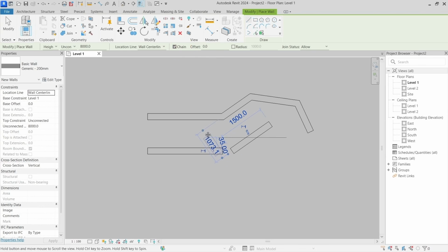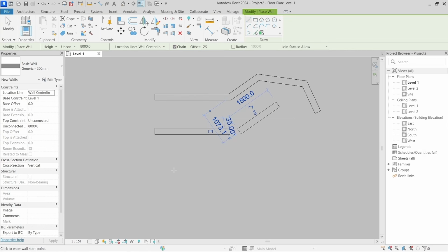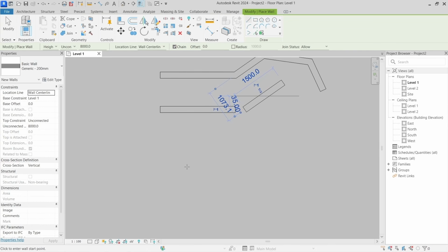Okay, now let's talk about how to put exact numbers inside of these walls if I'm creating them. So let's say that I will first start with my left mouse button, and now I want to create a wall that will be, let's say, 4000 millimeters in length.